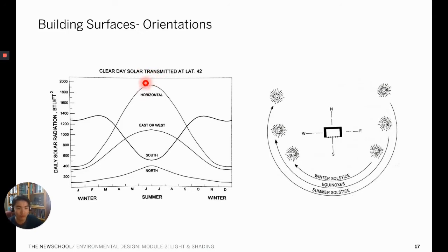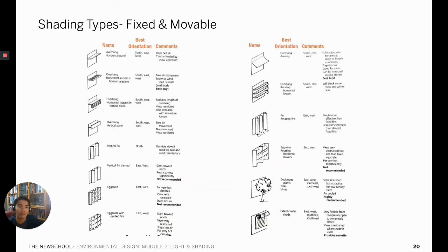Therefore, the horizontal surface where the skylights are located needs effective solar shading during the summertime. If shading is the main concern and passive heating is not required, then a fixed overhang may be used. If both passive heating and shading are important, then a movable overhang should be used.